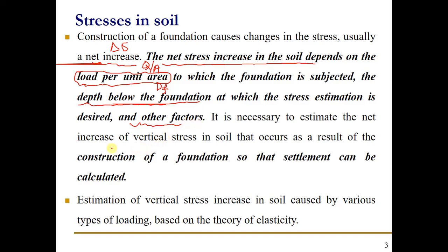It is necessary to estimate the net increase of the vertical stress in soil that occurs as a result of the construction of a foundation, so that we can find out the settlement of that particular soil. So vertical stresses, then delta sigma, are used to find out the settlement in that particular soil.